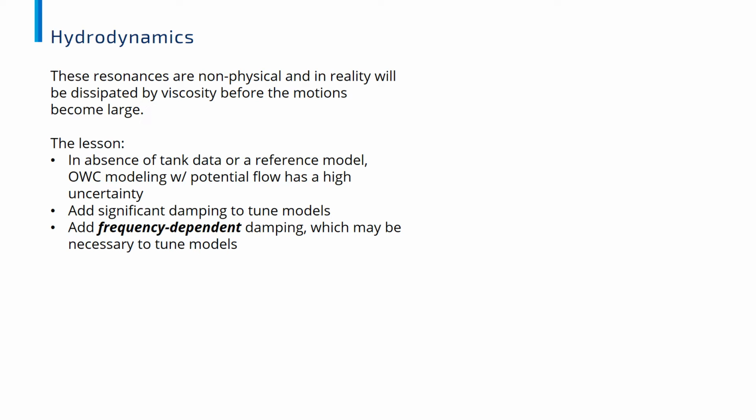While we're tuning them, it's not uncommon to see very large damping values need to be applied, particularly to the generalized body mode describing the motion of the free surface, to make the simulation predictive of physical reality. And depending on the success to which the boundary element method data can be cleaned up, it's also not uncommon that we need to vary the damping coefficient that we're applying to the generalized body mode with the frequency of the exciting waves.